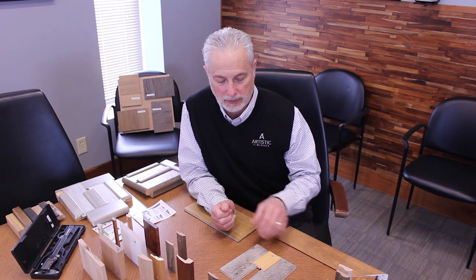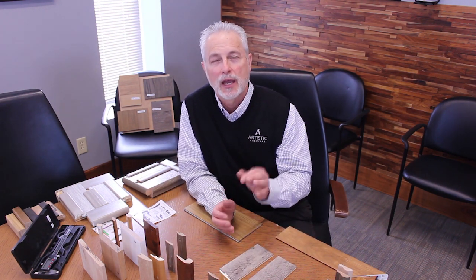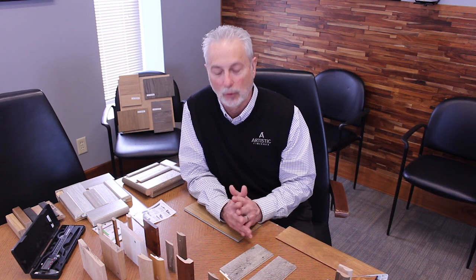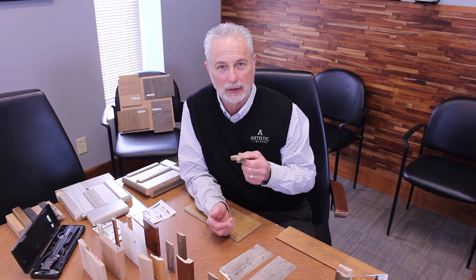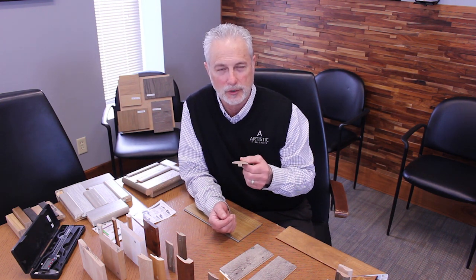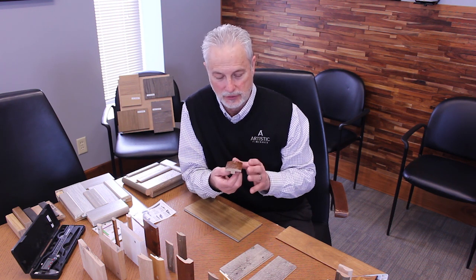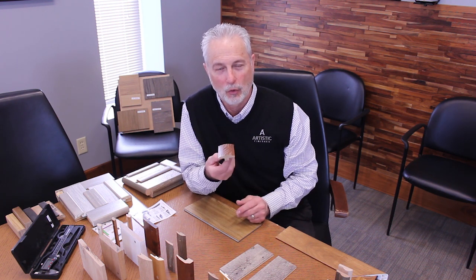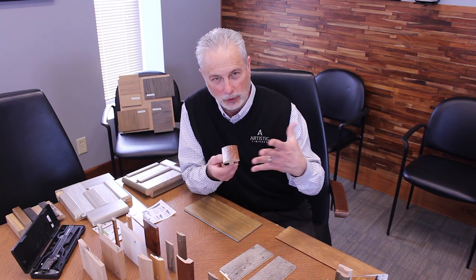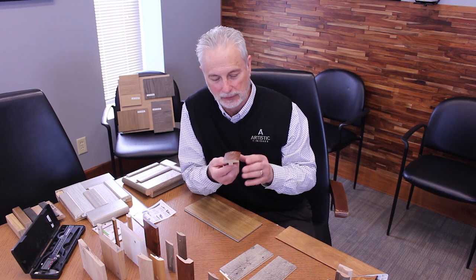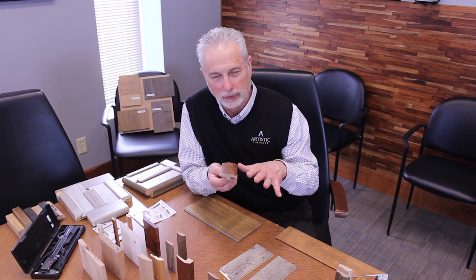So T-molds can be a very versatile tool, but primarily remember hard surface, equal height, and then they will perform admirably. They run all the way up even to the bigger models where you get into the thicker engineered, the solid core engineered wood floors, what have you. And in some cases you may put this over a 3/4 inch floor if you're going into another room and you're concerned about expansion. But typically they're used with floating floors, engineered floors, and floors of lesser height.